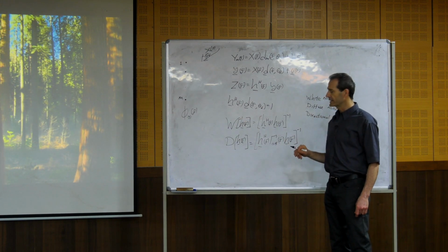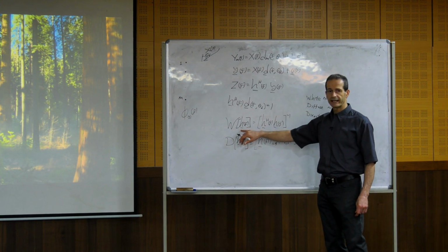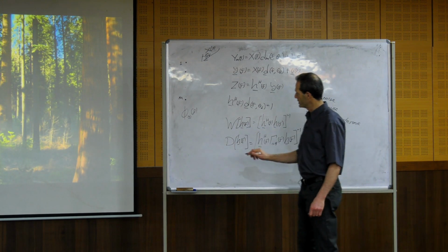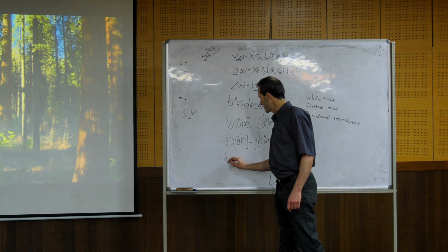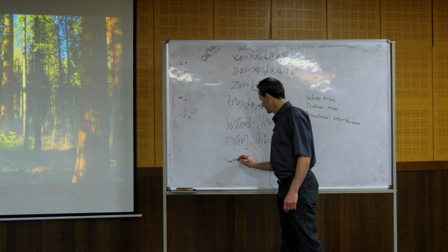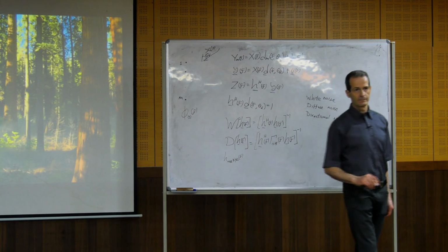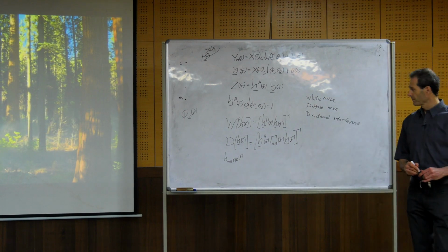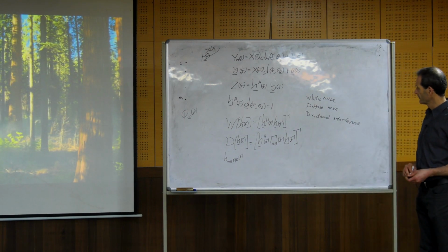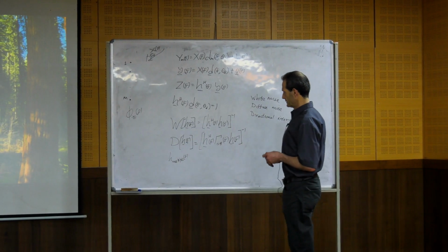So we can design a maximum white noise gain beamformer. So we can achieve H max white noise gain. Okay, and this is for, we talk about narrowband, okay?